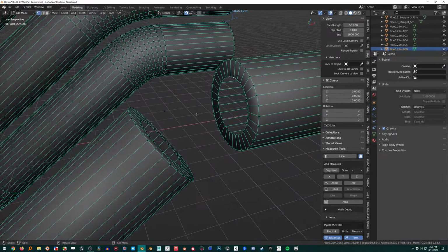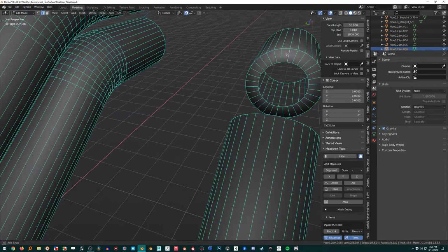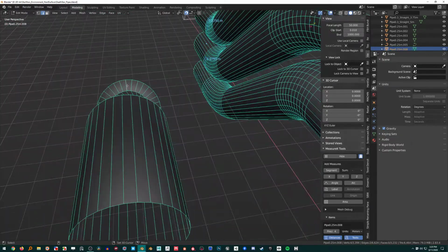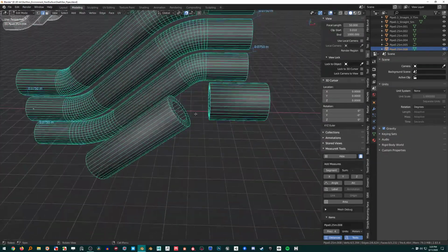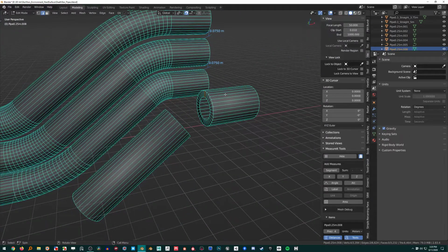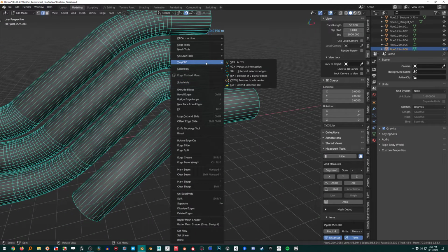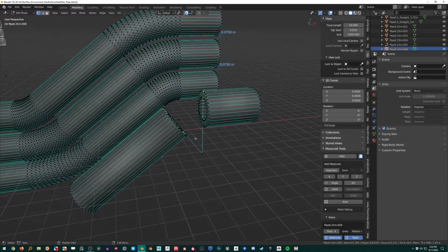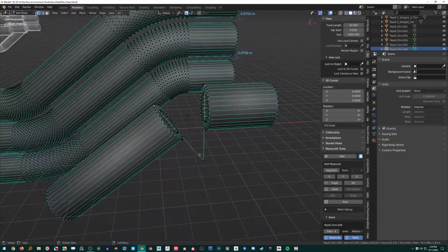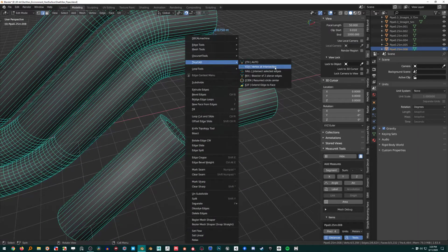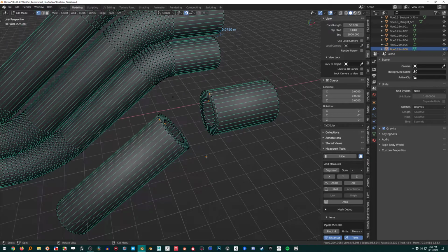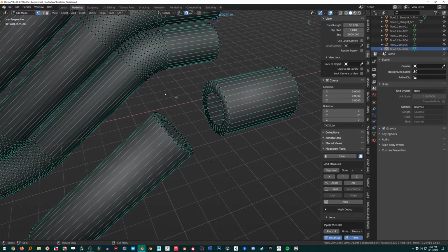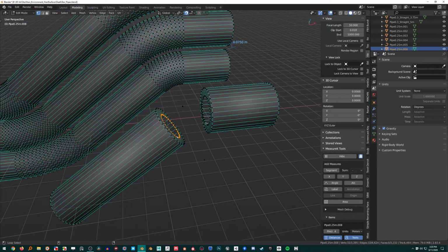So I'm selecting both of these edges, and there's an add-on that comes with Blender called TinyCAD. It has two tools where Auto will make edges to that intersection point, or the vertex at intersection, which just creates a vertex wherever they meet. So I put the vertex there, and you can see I left that one the way it was.